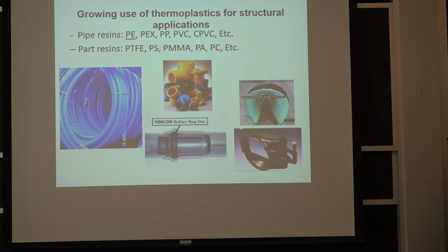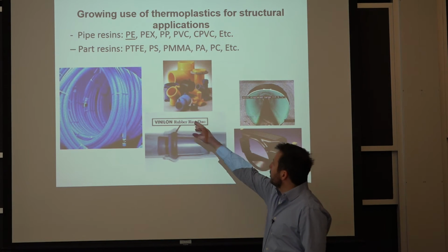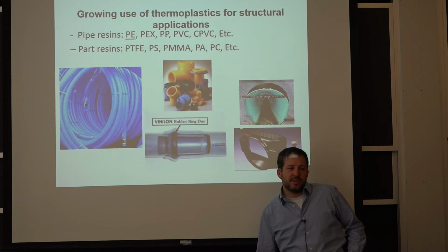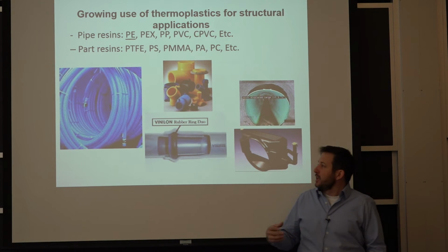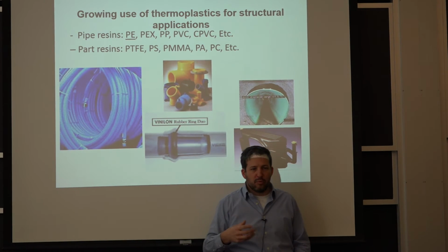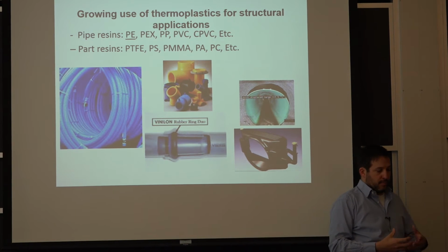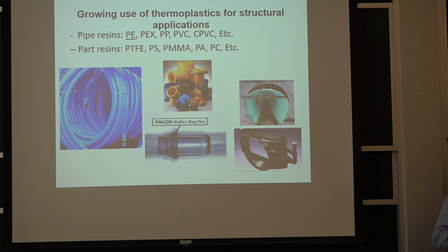So plastics like the one I circulated, you can make them in very, very complex shapes. You have them here, but they're not exactly as resistant, again, because they are cast. So it's easy to make this one in a very robust, transformed state that doesn't have the spherulites in it. But when you cast, you pretty much are stuck with the spherulites. So that's why fittings a lot of times are made of a stronger material, whether it's a metal or a different type of plastic, to be able to sustain, first of all, the extra load.